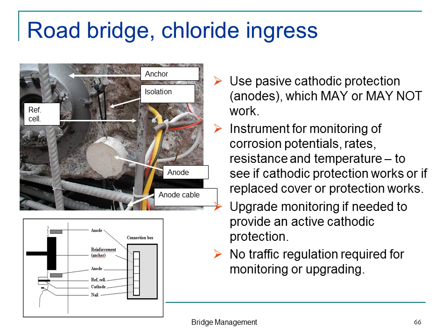What we did was we installed some sacrificial anodes, but we did also make sure to put in a reference sensor. We made sure that we installed enough to actually measure what was happening in here, because the repair ought to work. The sacrificial anode ought to work if the repair didn't work.